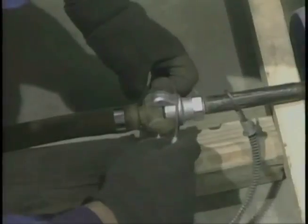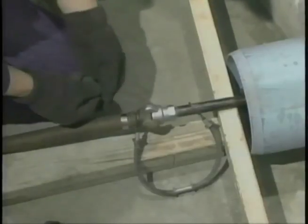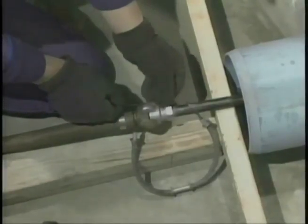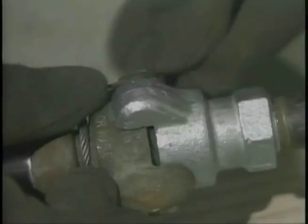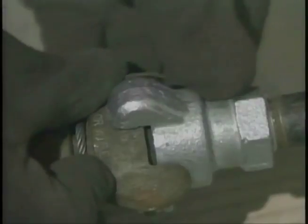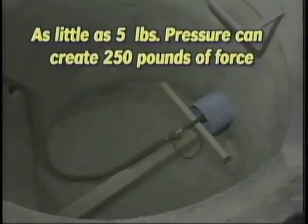The whip check is a safety measure in case the airline should break. The whip check prevents the pressurized hose from whipping out of control and causing injuries. Attach tie wires to the connections. This second safety measure prevents the fittings from coming apart. Under no circumstance should anyone be in or near the manhole during the test. As little as 5 pounds of pressure can create 250 pounds of force on an 8-inch plug.